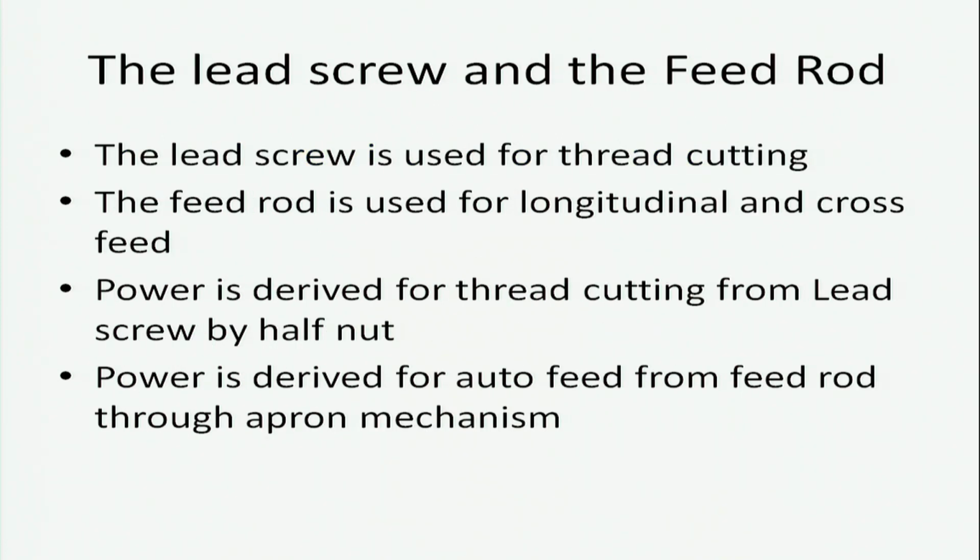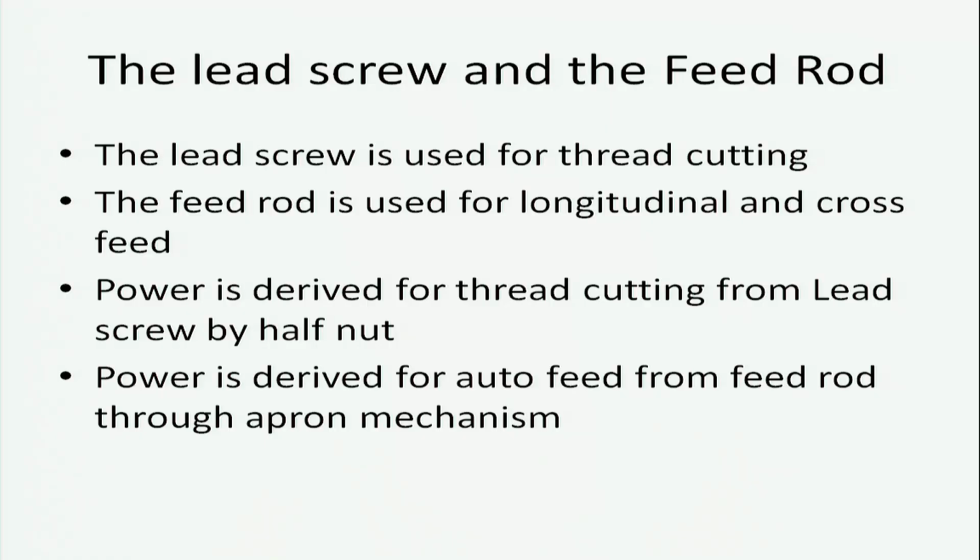One student has inquired, what is the basic difference between the actual usage of feed rod and lead screw? The lead screw is basically used for thread cutting, and the feed rod might be used for automated longitudinal feed or automated cross feed, either this or that.